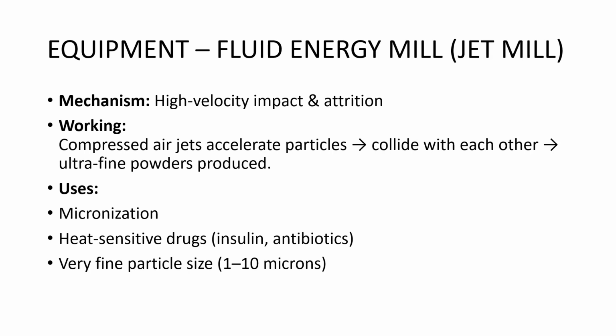Now let's look at the fluid energy or jet mill, which is used for ultrafine powders. The fluid energy mill uses high velocity air jets to achieve ultrafine particles. Particles collide with each other at high speed and reduce in size. It is excellent for heat sensitive drugs and can produce micron sized particles.